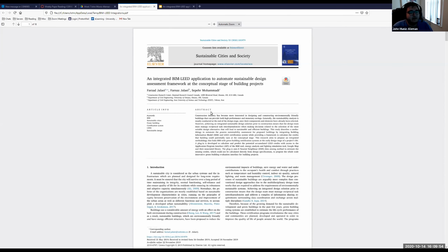On the right side of the screen, these are the LEED version 3 categories. Their main categories: sustainable site, water efficiency, energy and atmosphere, material and resources, indoor environmental quality, innovation and design process, and regional priority. The end product will be using LEED version 4, in which sustainable site is split into sustainable site and transportation requirements, which is transporting materials to the site, because that obviously takes carbon emissions. We'll get a little bit further into that.